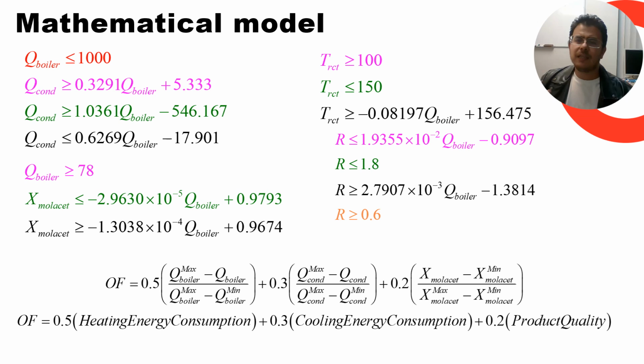When we analyze several feasible regions, we can obtain a mathematical model. In this case, the mathematical model is a linear programming model because all constraints are linear. The complex model considers the mass equations, kinetic models, thermodynamic models, and reactor design equations. It's reduced to only 15 equations: 14 constraints for the variables, and one objective function.